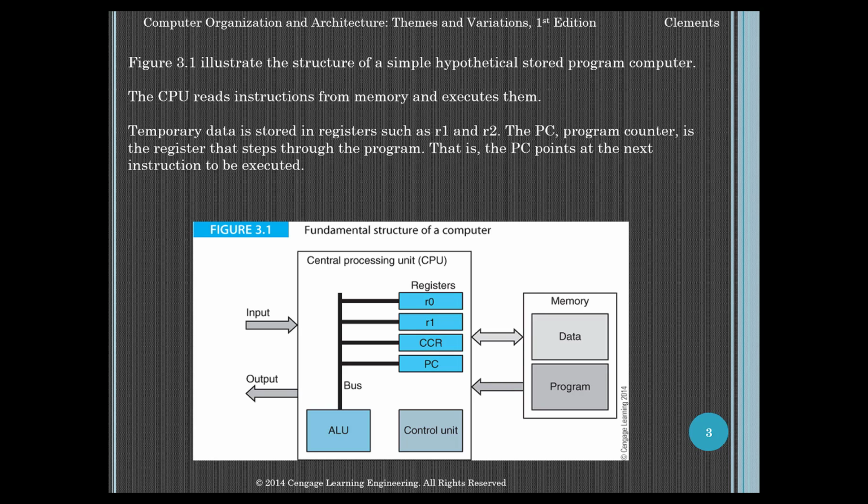And then probably the most important register in the CPU is its program counter, which you can see here on the figure is named PC. This contains the address of the next instruction to be executed. So remember, instructions happen in a sequential way, right? They're all queued up to happen in the order that they were received. Once the CPU is done with the current instruction, the PC, which is also sometimes called the instruction pointer, don't get confused, those are the same thing, tells the CPU what it's going to do next.